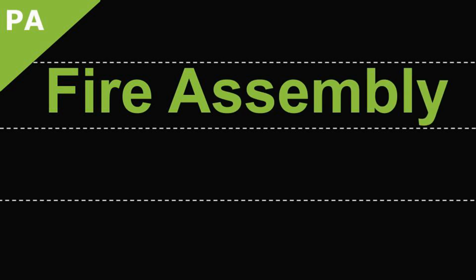Fire assembly. A fire assembly is a system and assembly specifically used for structural fire resistance and fire resistance rated construction. Fire assemblies can describe a fire door, a fire window, a fire damper, or a firewall. The various types of fire assemblies, such as a firewall, fire barrier, fire partition, or smoke barrier, are some examples detailed in IBC Chapter 7 Fire and Smoke Protection Features.